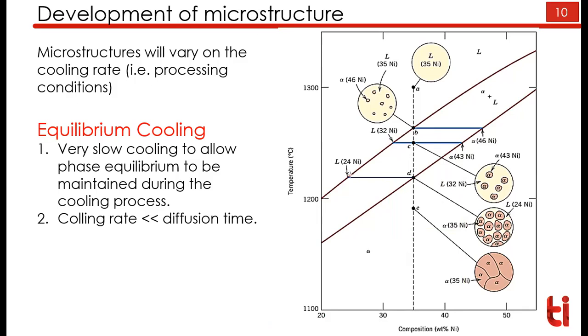So this is the temperature. Okay, we have to find the composition, how much liquid? This is my composition of liquid: 22% nickel. And solid is how much? So in solid, I have alpha nickel 35%. That is my actual original alloy composition I've taken.